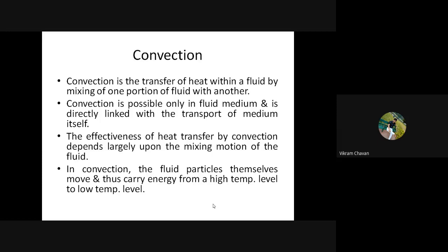In the last lecture, we covered the electrical analogy between the electrical circuit and Fourier's law of conduction. Analogy means finding out the similarities between two different systems, and that analogy is useful to find the thermal resistance for conduction heat transfer. We discussed how to find RTH, the thermal resistance for heat transfer in conduction. Then we discussed simple problems on Fourier's law.